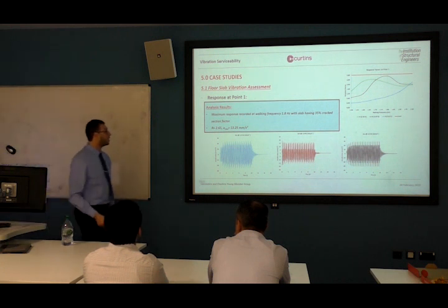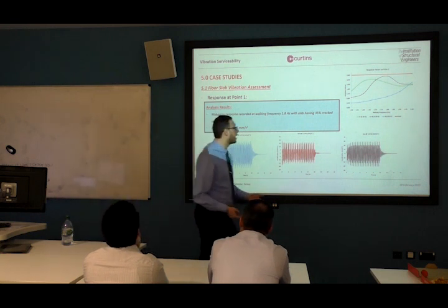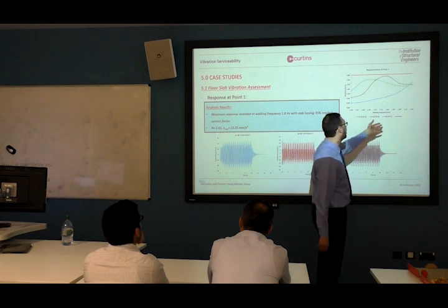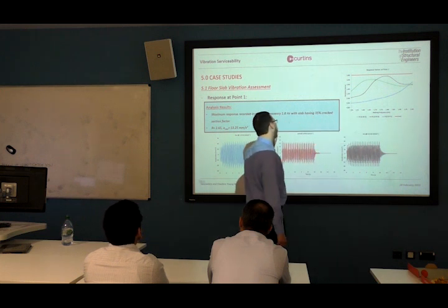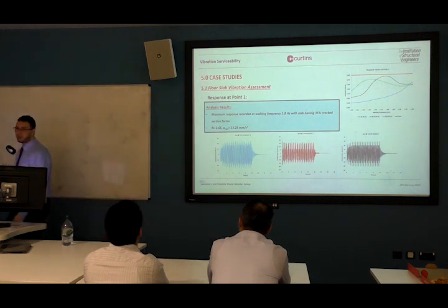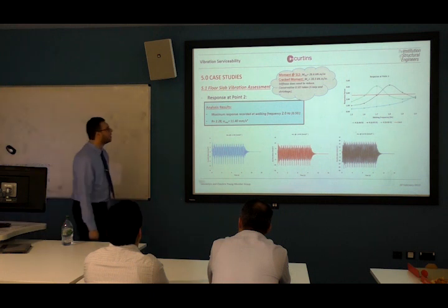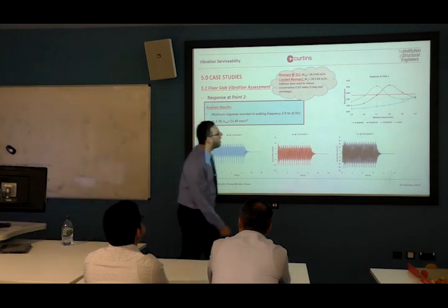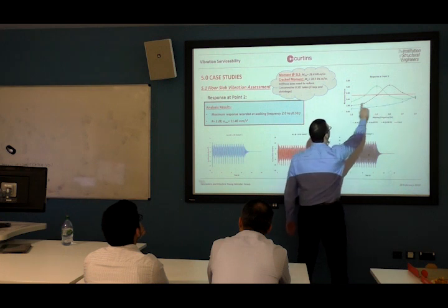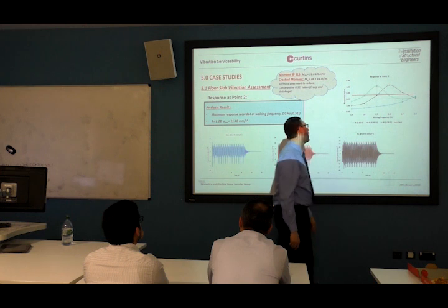Okay. So the maximum response, we've checked it for 3 different cracked properties at 0.3, 0.35, 0.5, and the limit, everything is fine. So this is for the first mode shape for this slab. So everything was okay. Second point, we've done the same analysis, but we're getting a bit higher results at 1.8 and 1.7, and this is for 0.3 and 0.35.